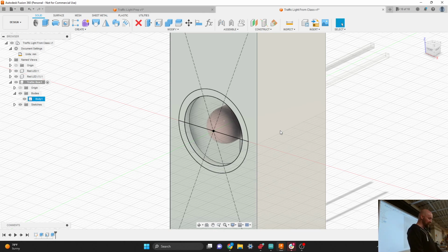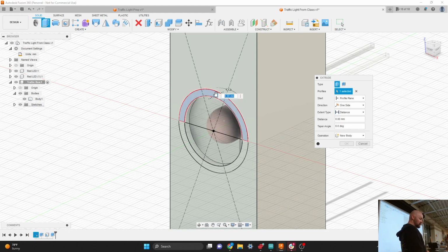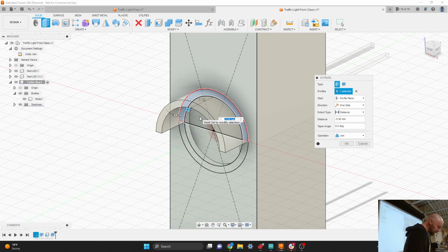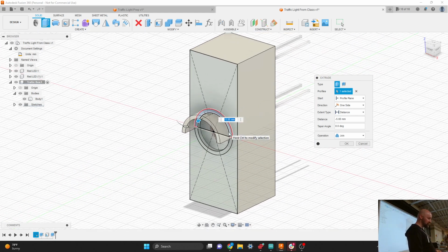Now, let's go ahead and extrude again. We'll extrude outward our little face shield, or our little shield here. I'm coming out negative 5 millimeters, but it could be 5 millimeters for you, depending on how negative and positive work on here. Those are always different. I am going to choose join. Join is a fine operation here.